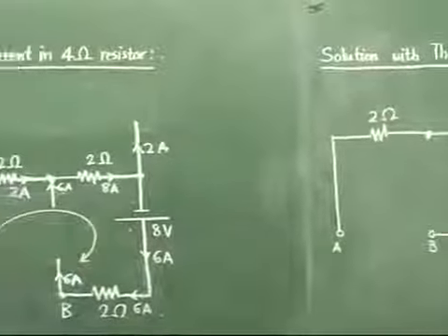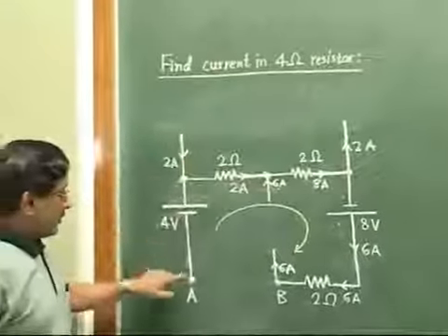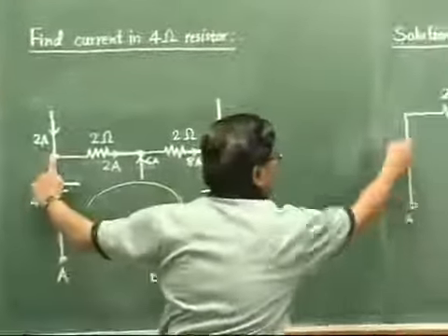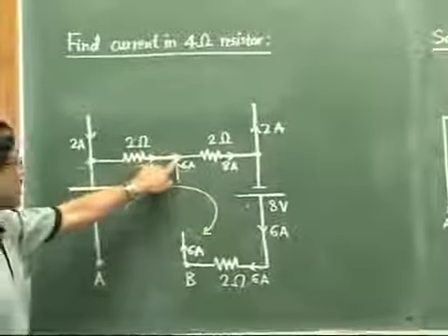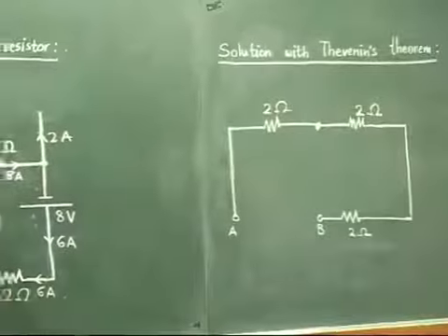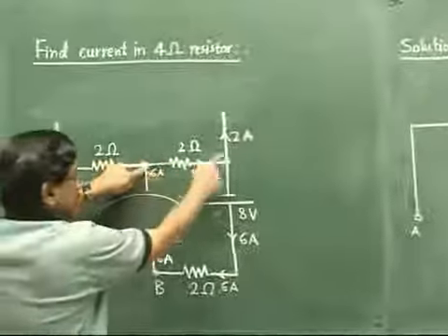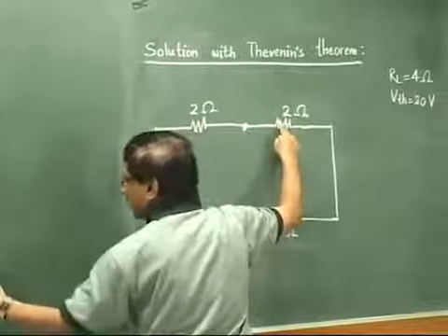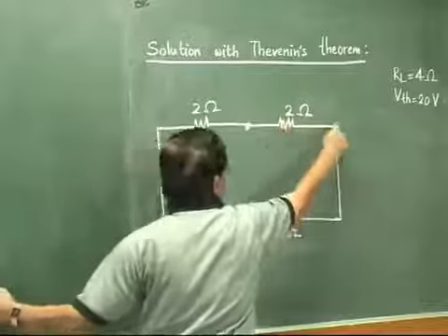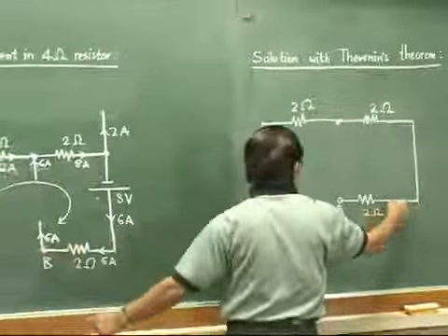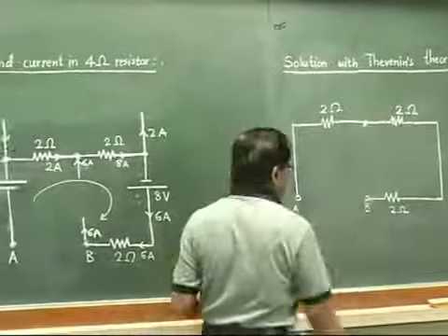Again, see clearly in the circuit. Point A here, this battery is shorted, so it will be from this to this. Then this to this is 2 ohm, that way we have shown here. Then again there is open here, so this to this is next 2 ohm resistor here. So we reach here. Then this to this source also to be shorted, so we come like this, short circuit. Then this to point B will be 2 ohm, and again nothing there.